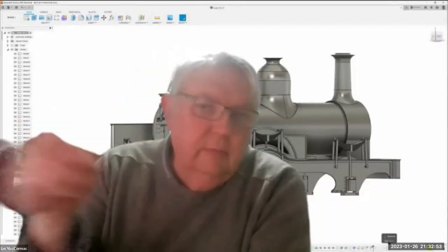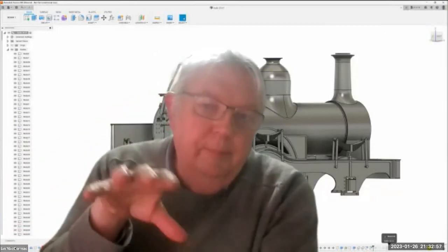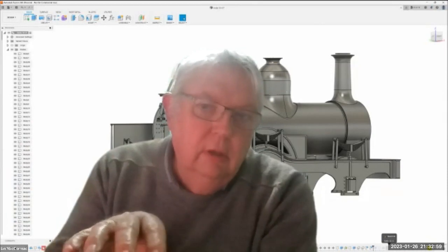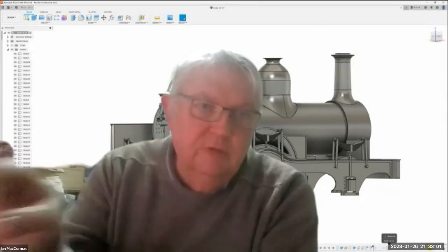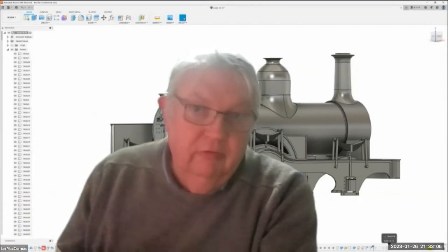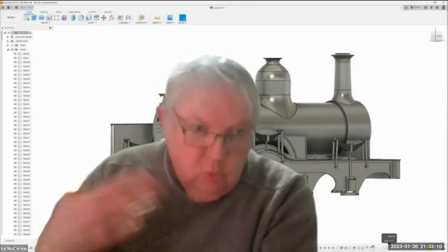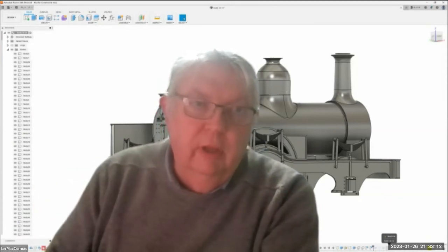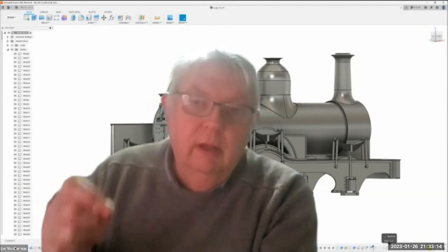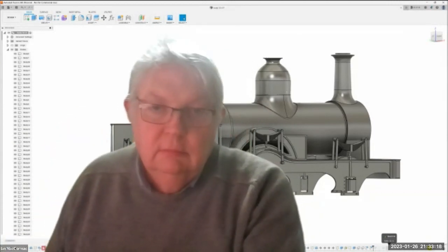Again, there's one of those tank clean options in the menu now. You just run that for 10 seconds and just peel the bottom layer off the FEP, and it all comes off. So, again, it pulls up all the muck and anything else that's on there. I only do it for 10 seconds, but it's enough to get everything off if you have had a mistake.